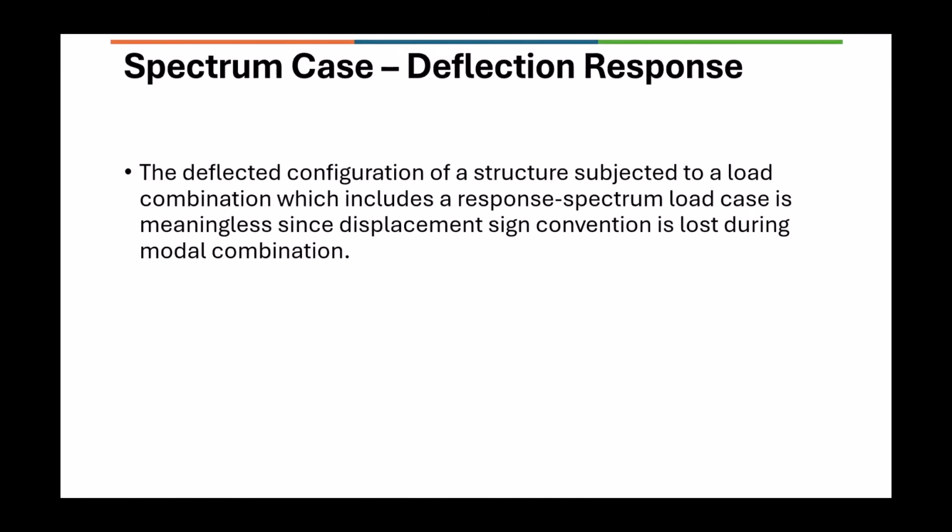So one option which we usually recommend is to perform the response spectrum analysis, and from the story shear diagram or from the table output, you can get the story forces and define a user-defined load pattern for the seismic and apply these forces as diaphragm forces and perform the analysis and check for all the serviceability requirements. That you can do easily. It is also useful in transferring such forces to the foundation design also.